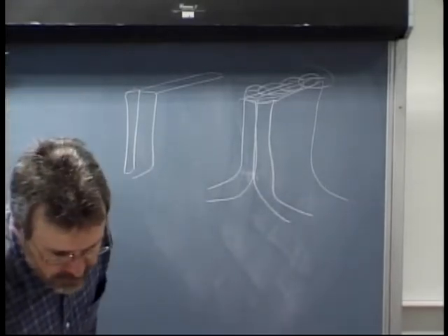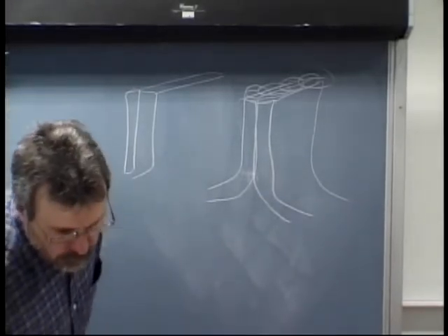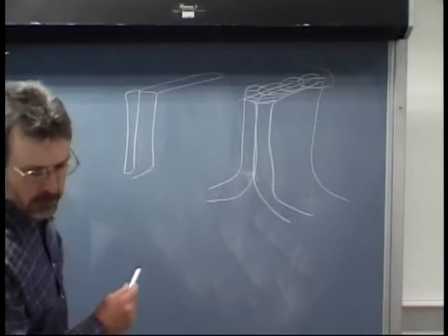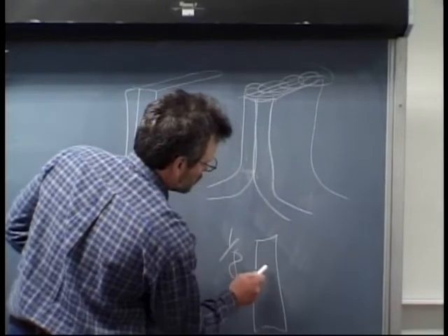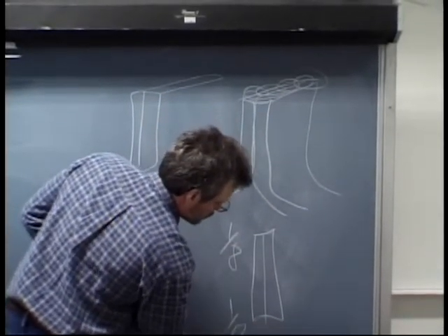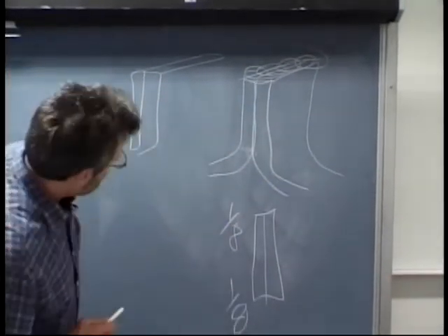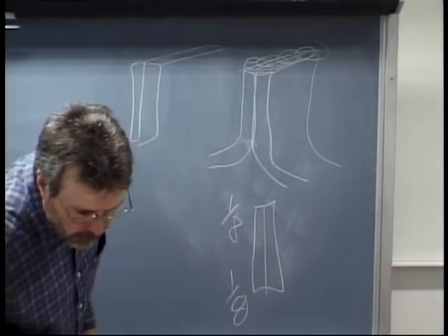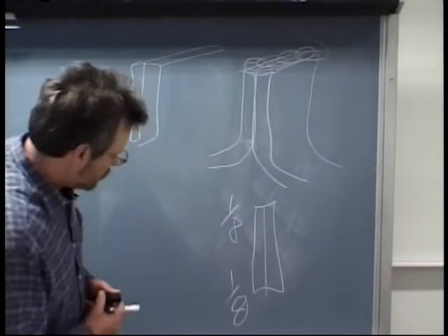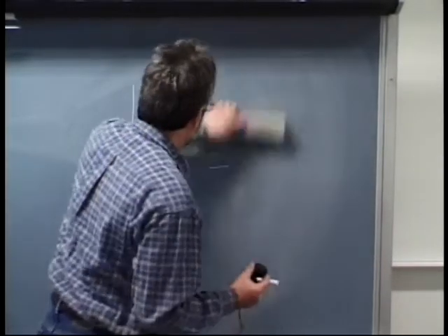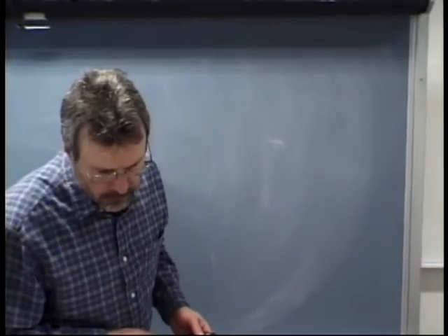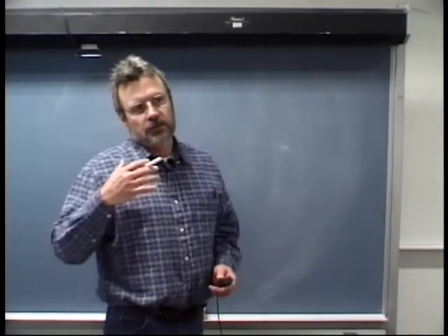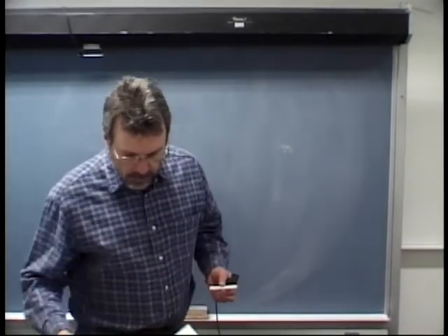In our book, your example, A, shows the symbol as 1/8 inch and 1/8 inch, like so. And then right below, we have the melt-through symbol. And there's a difference now. You notice that the melt-through symbol is black, okay? That's to distinguish it from a back weld.